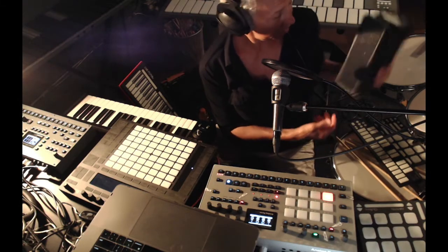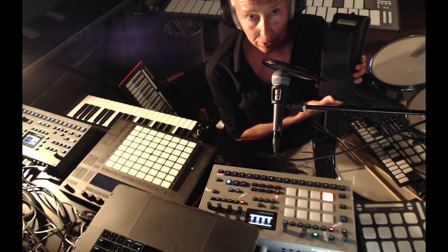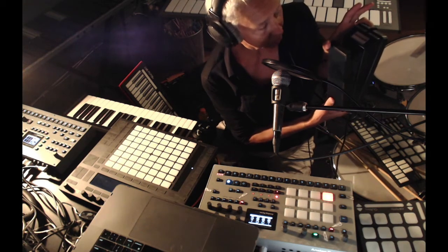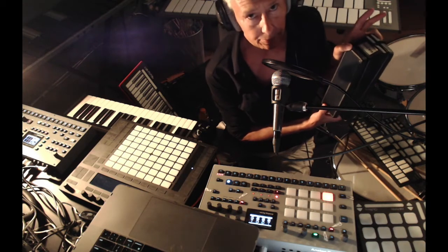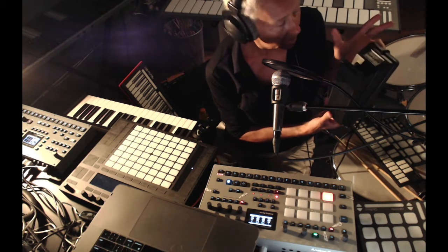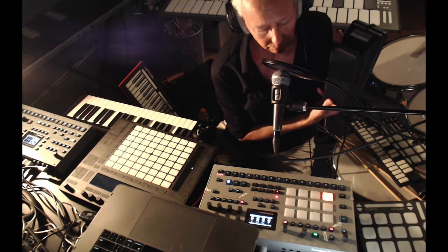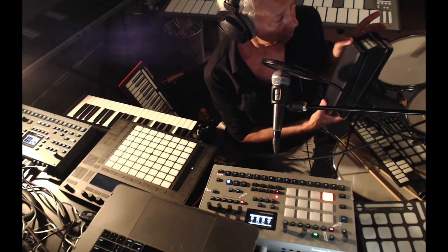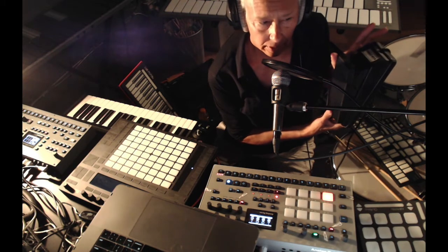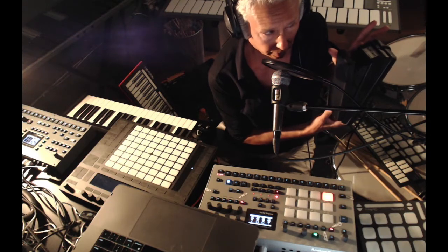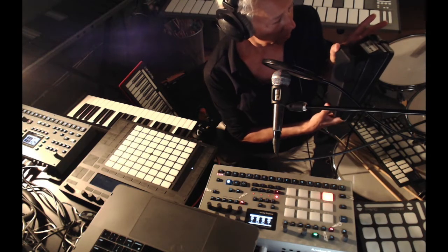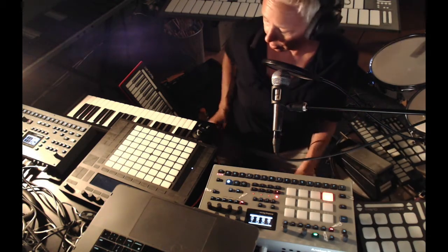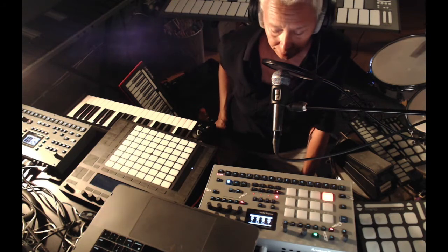This expression pedal is sending 0 when it's all the way down. It's called a continuous controller in that it sends just a stream of data as it goes up to 127 and all the way back down. This could be a volume pedal, which is continuous controller channel 7, or you could set it to be the cutoff on a filter sweep, 72, I believe, in general, and just about anything, if it's plugged into a keyboard that accepts expression pedals.